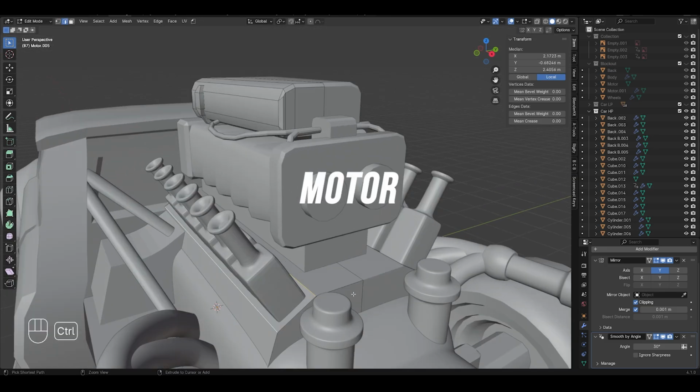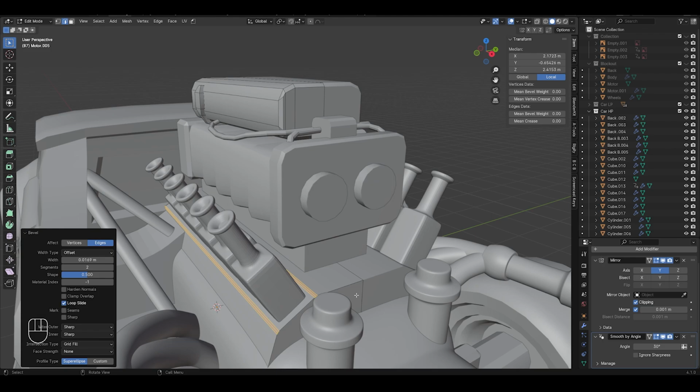In this part I have to be very careful because we cannot apply the Bevel Modifier everywhere in the same manner, which actually means with the same settings, because all the forms, especially in hard surface, have specific curves, specific lines, and specific characteristics according to their materials.